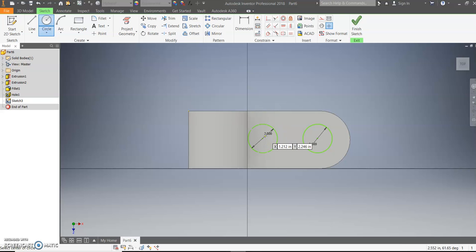Now they're not properly located, so next I want to locate them by dimensioning them. So I'm going to click the center of my circle, and then the outside edge of my circle, and it should be a distance of 2 apart. I'm going to hit escape since I didn't get the right location. And now hopefully I can make these concentric to one another. In this case, it looks like it's trying to do it from the center of the circle. So I want that to be a distance of 0. So I'm just typing a 0 there. And that's going to make it a concentric circle.